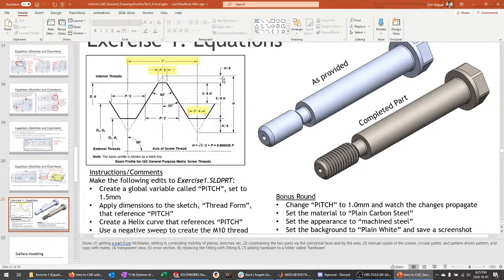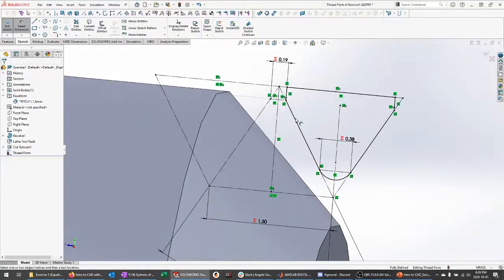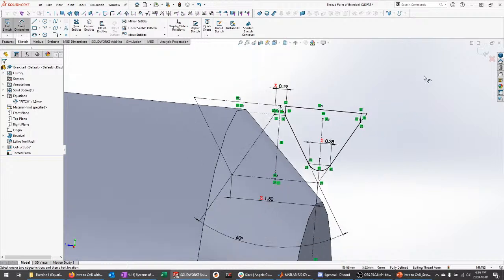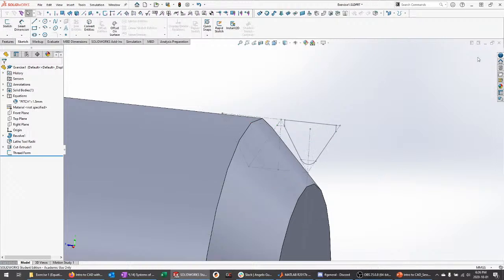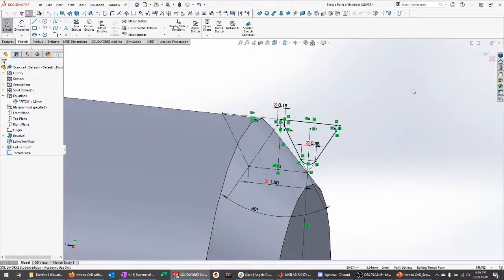You can see, here this is effectively just a drawing labeling all of these dimensions. We don't actually need all of these dimensions in order to fully constrain the system because we've used a bunch of constraints here in the construction geometry that does the same job. Anyhow, so we're going to back out. By the way, when you're exiting a sketch, the X here is exit and do not save any of the changes you just made, and this is exit with saving the changes you just made.